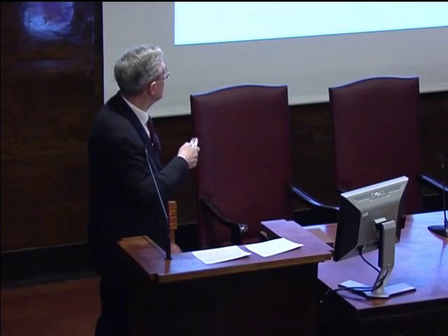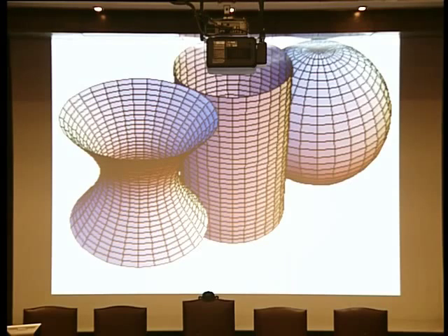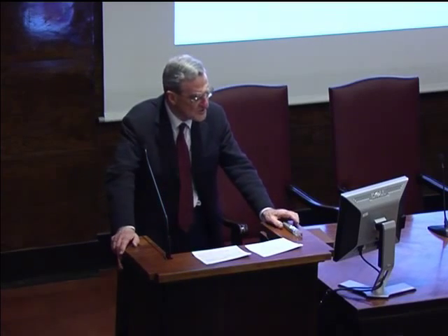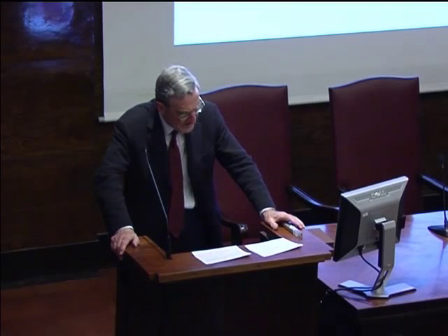By contrast, if we put a point load on the edge of a shell with negative Gaussian curvature, then that force, in theory, can be transmitted unchanged. It just goes straight through the shell and does not get dissipated at all. There is no dispersion, as there is with the egg, but a concentration of force. And this, of course, is where one has to question one's assumptions that one is making about the behavior of these shells.